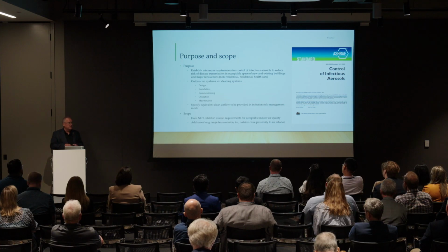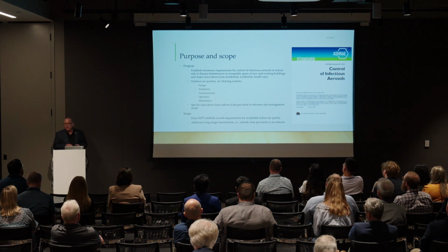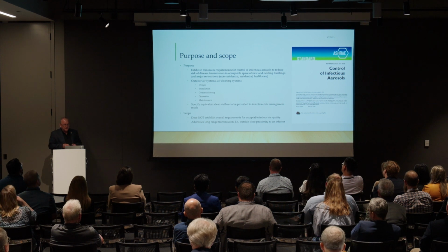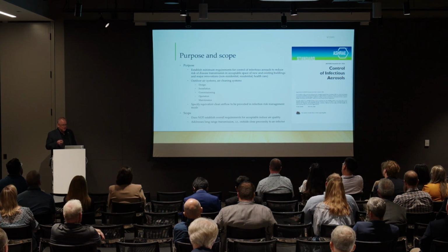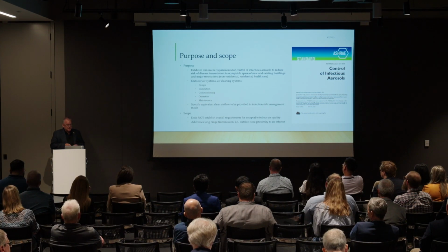And it's comprehensive, like other air quality standards: design, installation, commissioning, operation, and maintenance. You'll find all of those things in standards like 62.1. The really central concept of the standard is that it's all based on what we call equivalent clean airflow, which I'll explain. And I think that's really an important concept that eventually will affect all standards. What this is not is a new comprehensive IEQ standard. So it only applies to infection risk mitigation when it's needed.